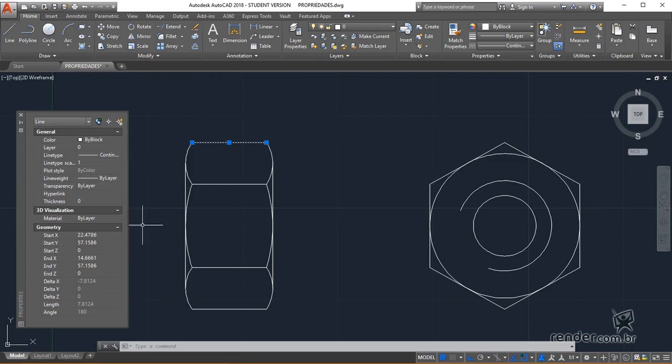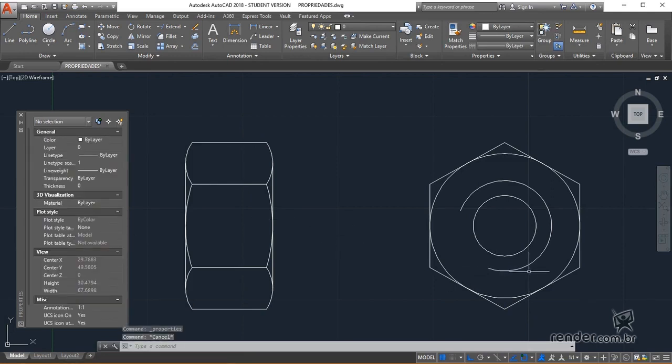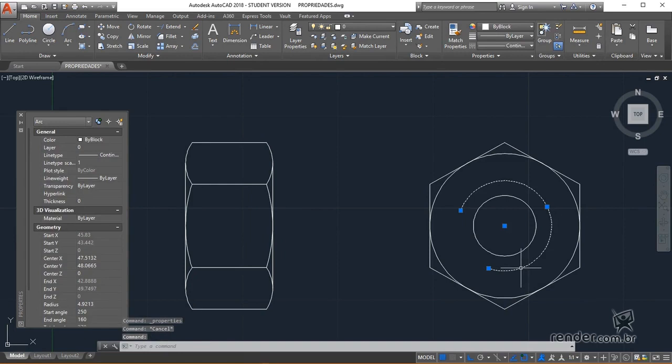Let's select this arc to see the information that can be modified. See that here we can modify the radius of the arc, its initial and final degree of opening, and the position of the center. We keep this information as it is, and in the Layer Definition field, we will modify it to the invisible layer, C.